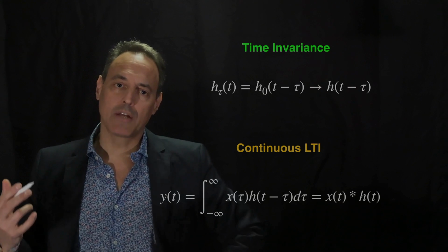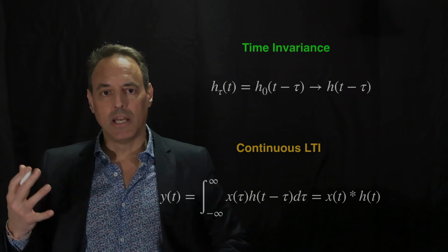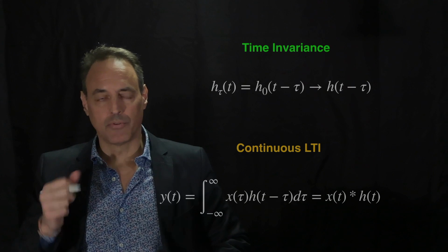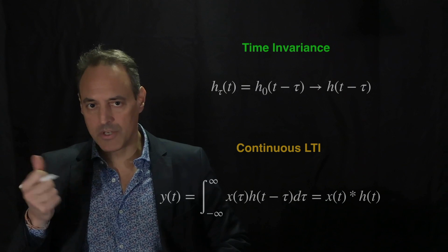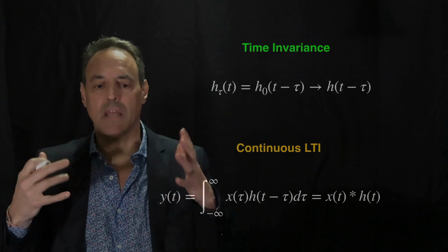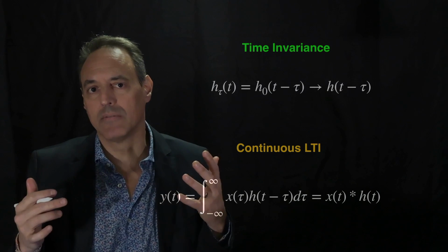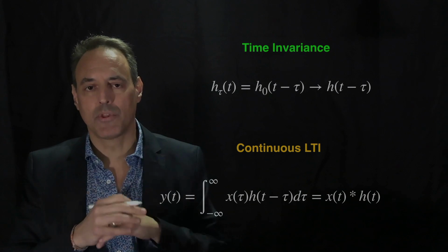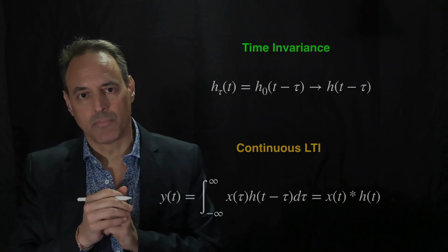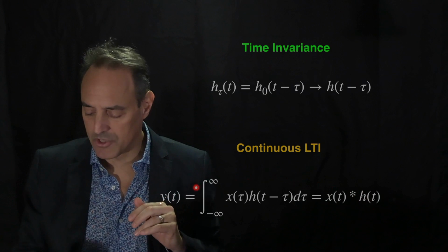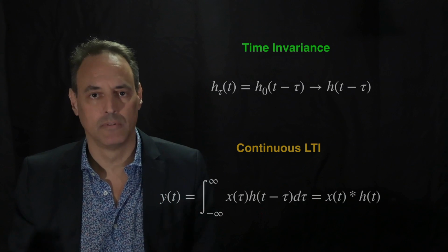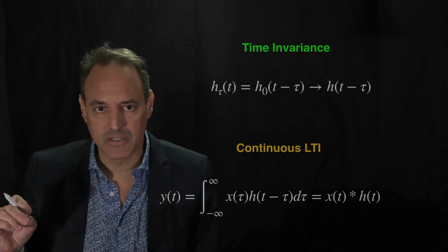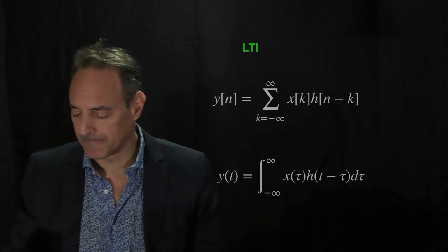If you're going to actually understand an LTI system, it's critical that you understand the response to the delta function. If you have a function or a differential equation that dictates the behavior of the system, your first objective is to kick the system with a delta function and understand the response. Once you have that, you have the general solution, which is given right here. So your objective is to understand, for a fundamental system, what its unit response is.